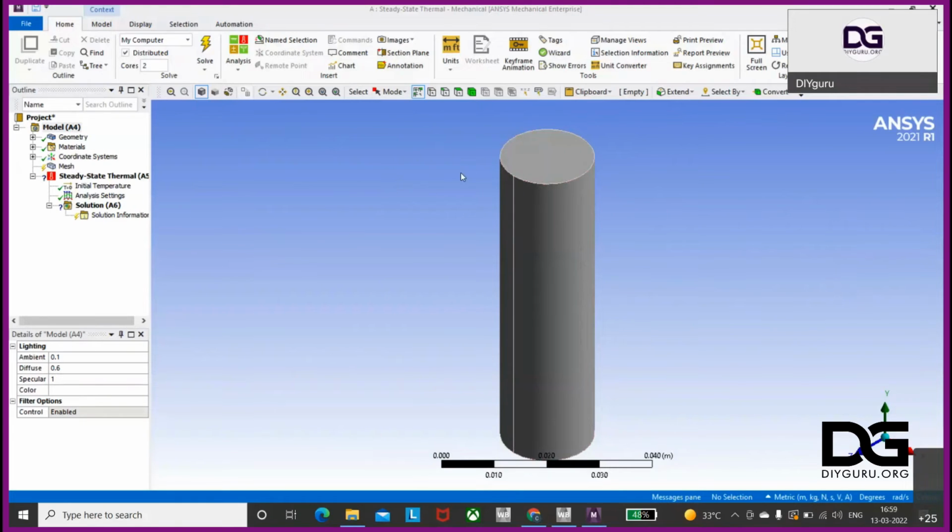Did you model a different anode and cathode for this, or is this a whole solid cell? This is a solid cell, a very basic cell. There's nothing inside over here. When you deal with ANSYS, you have to make your geometry as simple as possible. You cannot go with complex shapes. If I show you a proper cell, there are wedges and everything designed over there. You cannot have such things here because that will disturb my geometry.